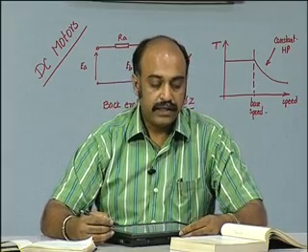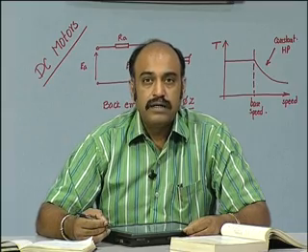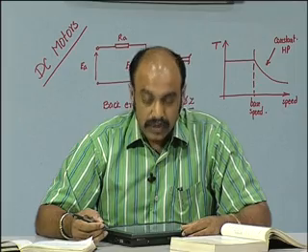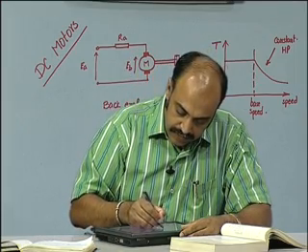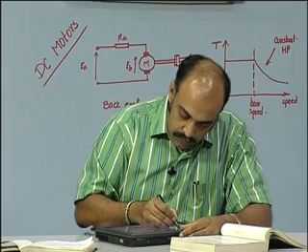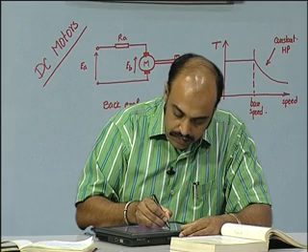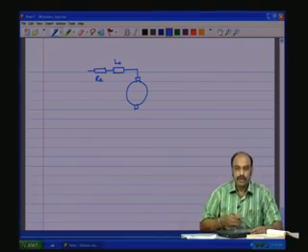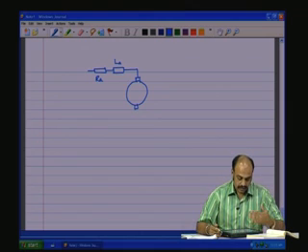So, now finally, we would like to discuss the state space model of the DC motor. It is very simple, just like in the case of the generator. So, we have the motor, we have RA. Now, I am going to include the dynamic element LA, which is going to cause the rise time and fall time of the motor.